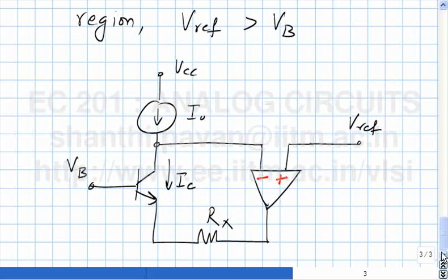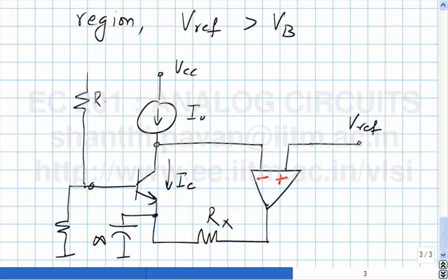If you want to make a common emitter amplifier, that is. What else do I need to do? I need to put a big capacitor here. Alright. So I need to bias this voltage without recourse to another voltage source. So RA, RB, I need to apply an input.